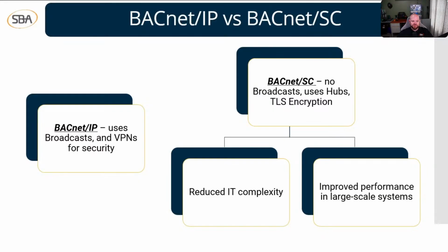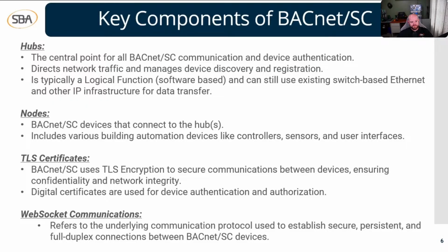So that's the differences between BACnet over IP and BACnet Secure Connect. And again, guys, remember, all your BACnet over IP devices, so your BACnet IP devices or controllers, you can bring them into BACnet Secure Connect. You're allowed to do that. The only thing that's changing is encryption, and like I said, it secures your communications a little bit more.